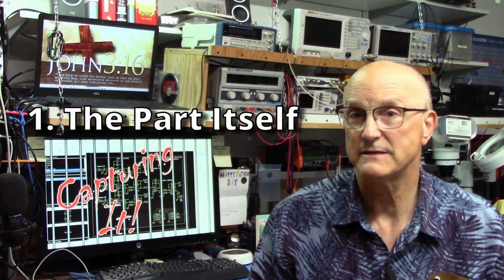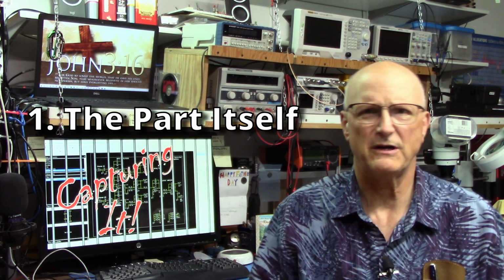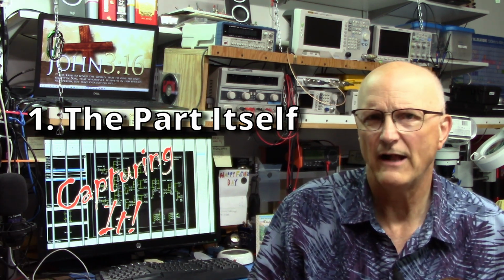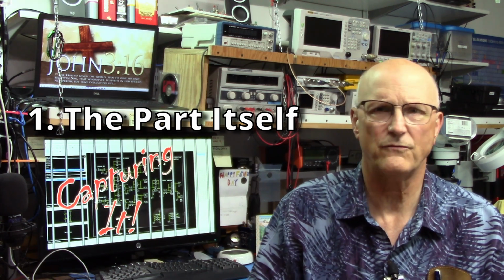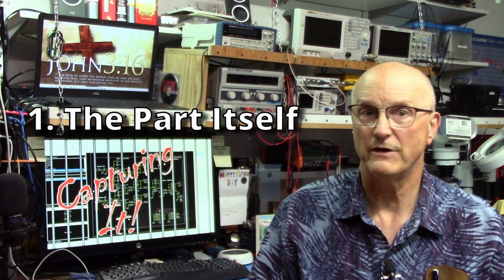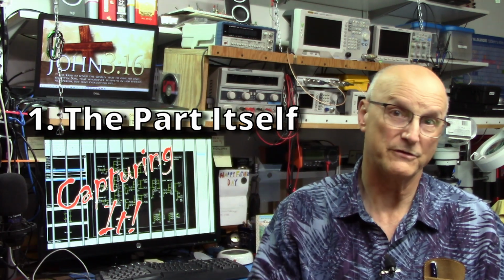I always begin this process by placing the active parts in the schematic first. When I place my active parts, I often start with the integrated circuits. And in every one of these cases, I have to pay attention to two things. The first thing that I want to pay attention to is the part itself. Now, consider the base part number such as a 74LVC2G04, which is a part number for a chip which has two inverters in it.